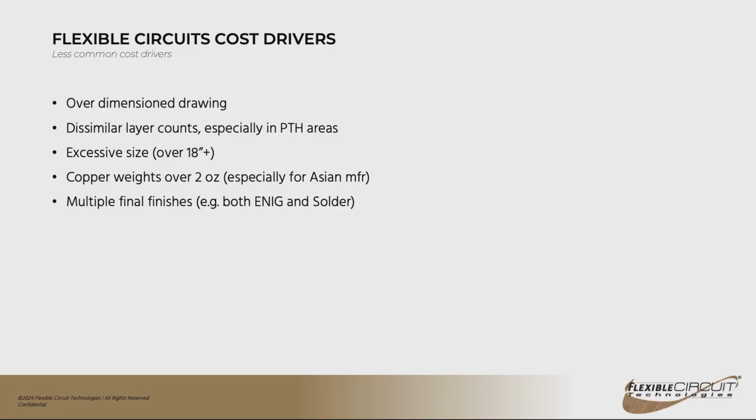A very common method of terminating flex circuits is a ZIF connector, a zero insertion force connector. And they're very inexpensive, and instead of having two mating connectors, you will have the ZIF connector on your rigid PCB and then basically just a pad pattern on your flex that goes into that connector and then it's clamped down. And they're very reliable. I've seen them used in applications ranging from helicopters to cell phones. They're inexpensive, and like I said, you're getting rid of one termination method there. You just have the one connector.